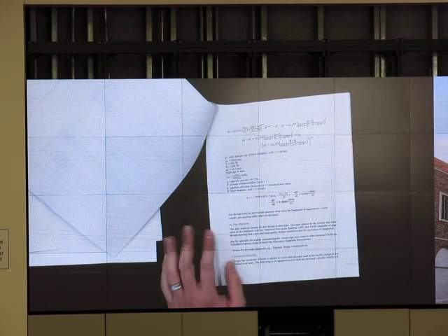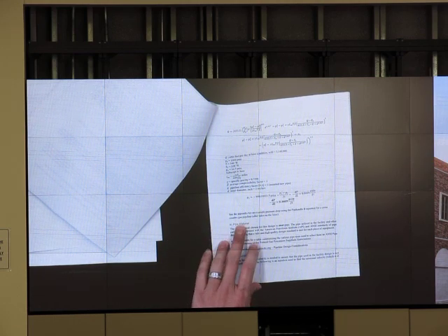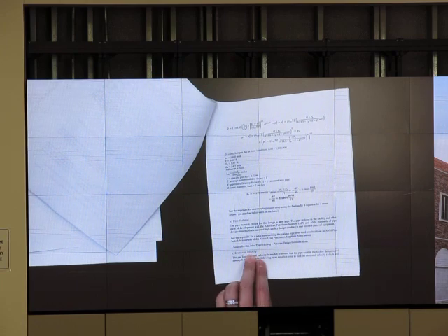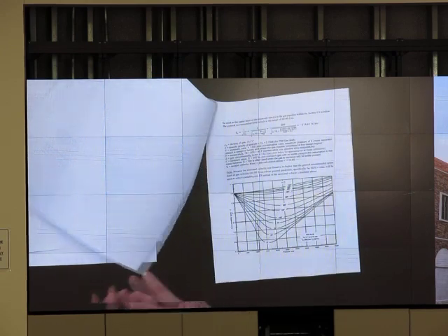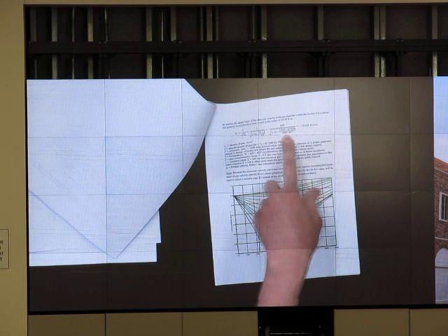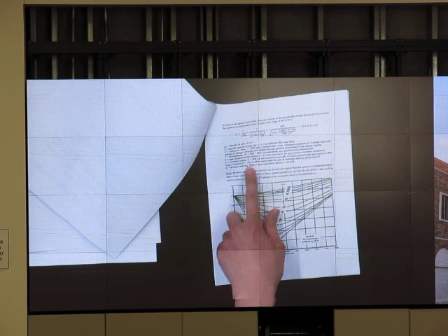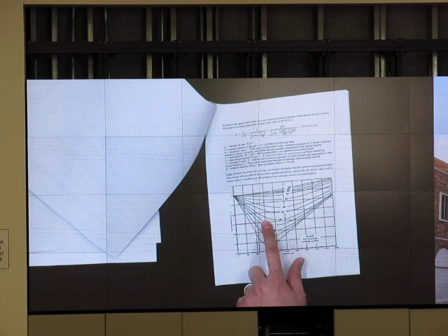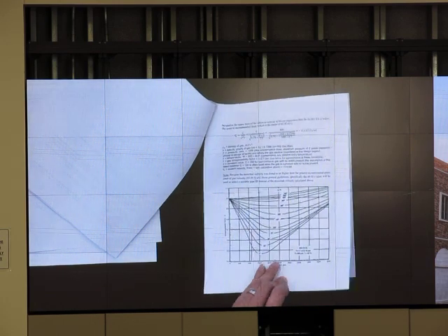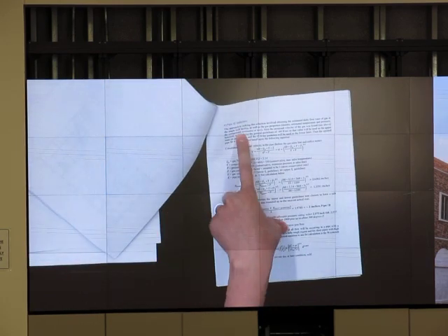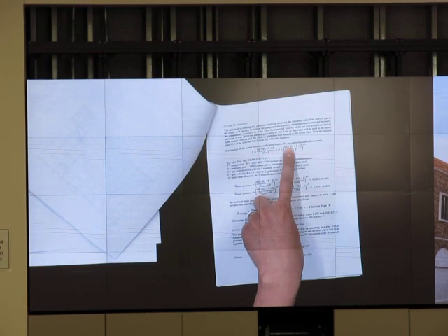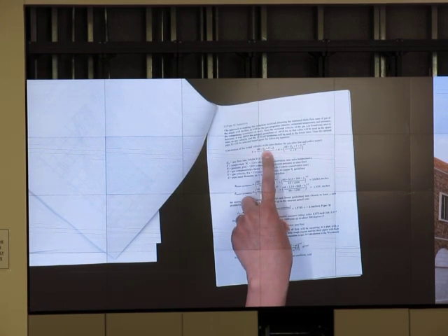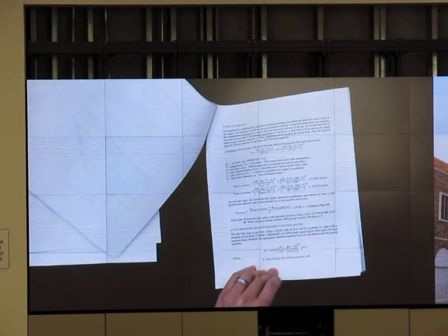which equation. So in this calculation example, pipe material, erosional velocity, how do they get the erosional velocity? They substitute the value in, that's what they get. And in this, they may need the compressibility factor, Z factor, and they show how they get it from the chart. Okay. And pipe side actual velocity calculation, that is V equals 60 something, that's the actual velocity calculation, right?